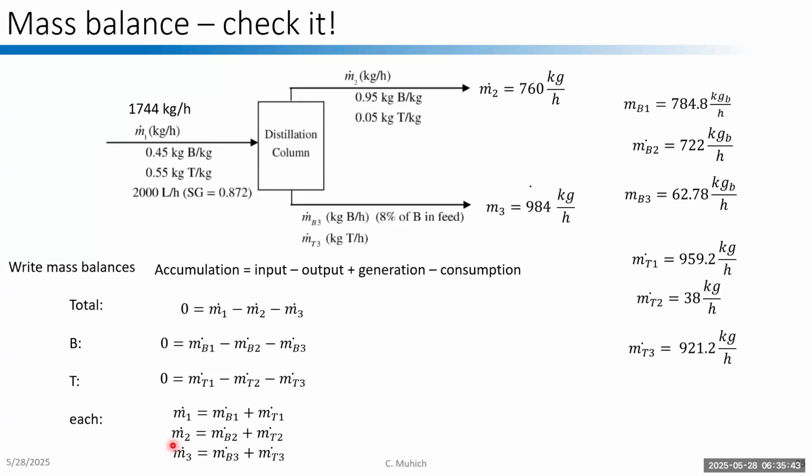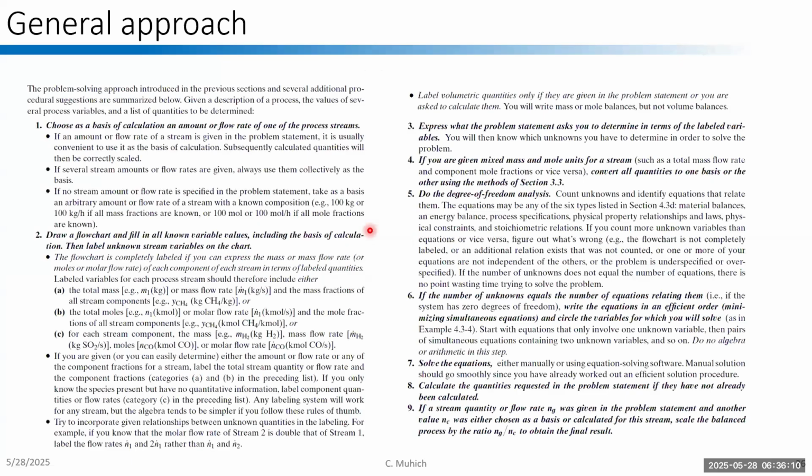All right, so we used the mass balance on the total mass flowing through the system. We used information on the mass of the individual species moving through the system. Okay, and then we used other information such as composition of the individual streams to solve our problem. All right, so let's go through.